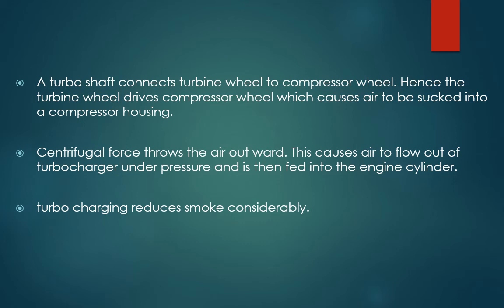If we supply that air at high pressure and high temperature directly to the engine, what will happen? In the pressurized air, the density will increase, but simultaneously the temperature increases. The increase in the density will not be significant, right? Therefore, we will trade off. We will try to reduce the temperature and give low temperature air, right? The point is that we want to increase the density only. The density of the air should be increased. When the temperature is high, the density would obviously keep on reducing.